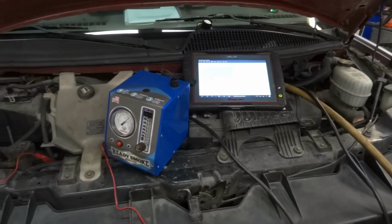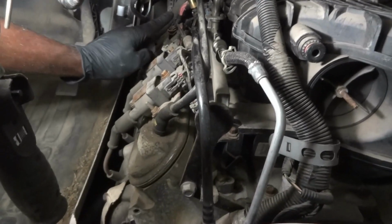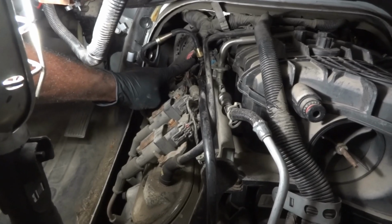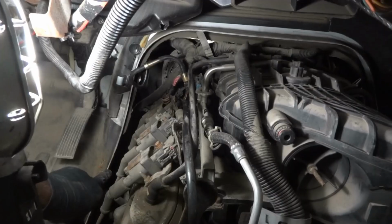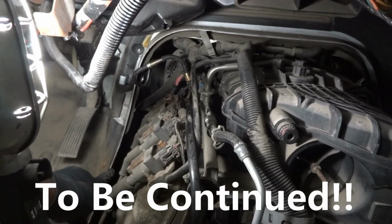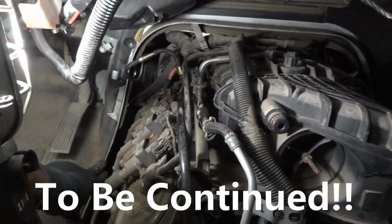So I'm gonna get my smoke machine out of the way. I'm gonna reinstall everything back in the vehicle. I'm gonna reinstall the engine cover, and I'm gonna reinstall the Schrader valve that goes into the evap system service port. After I put everything back together, I'm gonna bring you guys back up so we can test the O2 sensor wiring. So I will do that, and then I'll bring you guys back up.